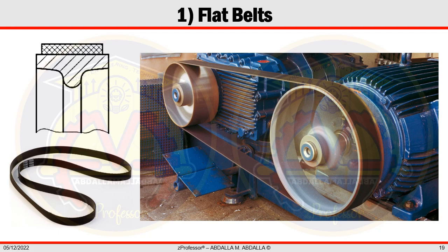The working surface is the area that makes contact between the belt and pulley. Frictional force on the working surface limits the driving force. At high speed and relatively low power, flat belts work well. Flat belts expand excessively when high power is to be conveyed, making them uncompetitive with V-belts.